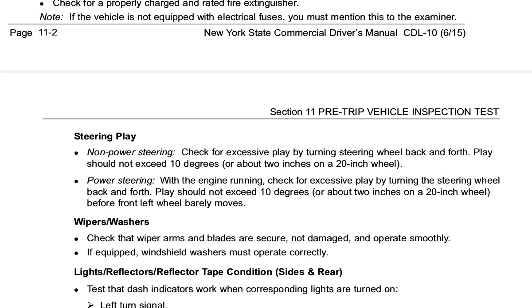Non-power steering. Check for excessive play by turning the steering wheel back and forth. Play should not exceed 10 degrees, or about 2 inches on a 20-inch wheel.